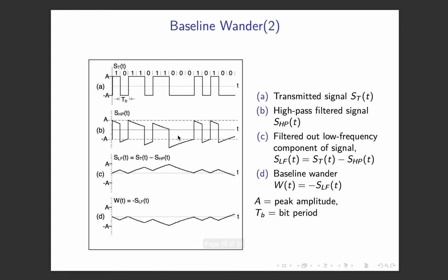Let's go back to the slide. Here you can see there are three consecutive zeros, and you can see these lower frequency components start falling, whereas the wandering starts increasing. So from there I can understand that if we take the difference between the number of ones and zeros, obviously this average line will shift around the mean, and that will affect it.